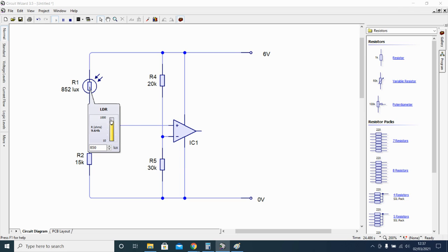We can watch as we change our LDR, we're changing resistance. Our resistance has changed here now, so there we go, we got 676 millivolts, just over half a volt now, because we've changed the parameters of our potential divider, and we got a different voltage in here now.